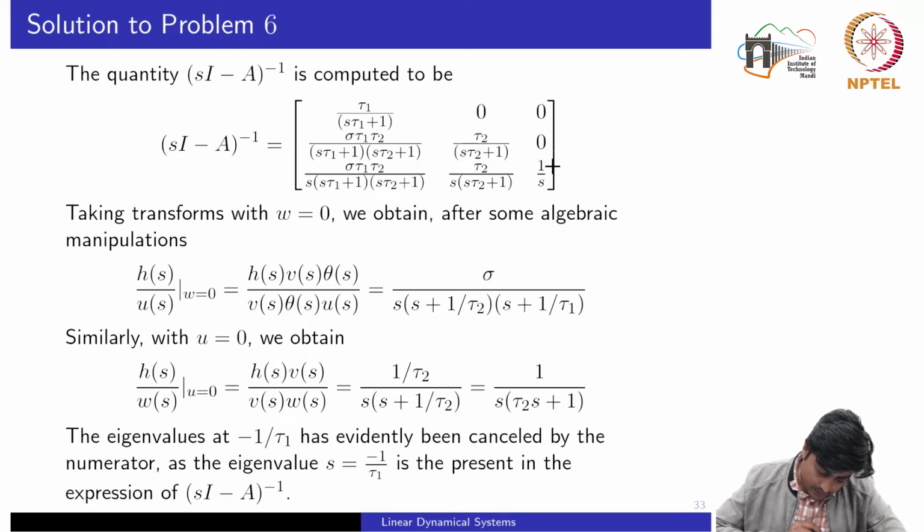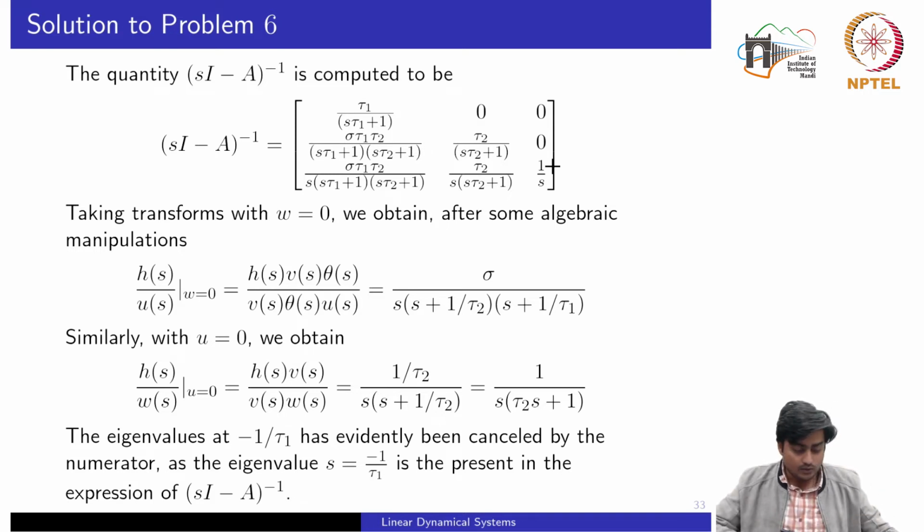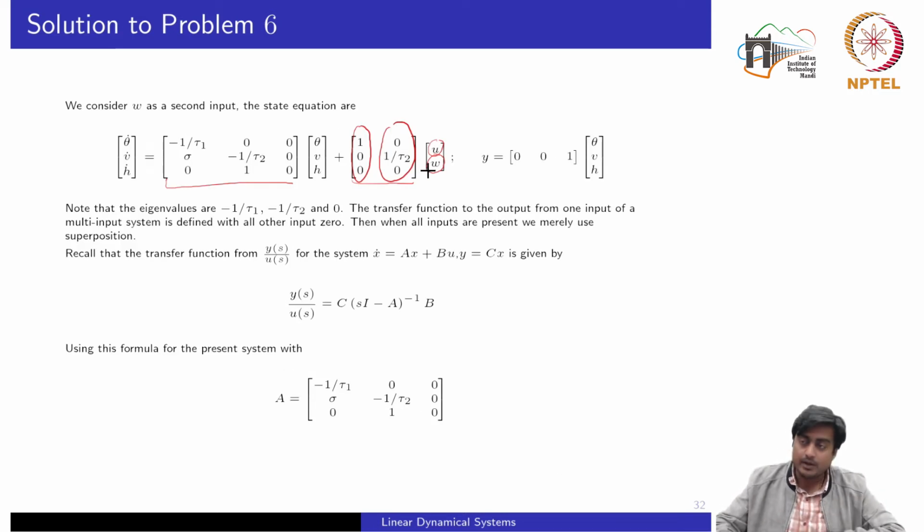Now since here we have two different inputs, the first test which you can do, once we have the A and B matrices, is to compute the controllability matrix and then compute the rank of that matrix. So this would be a straight test, but here try to visualize the controllability of the system without performing any tests first of all.